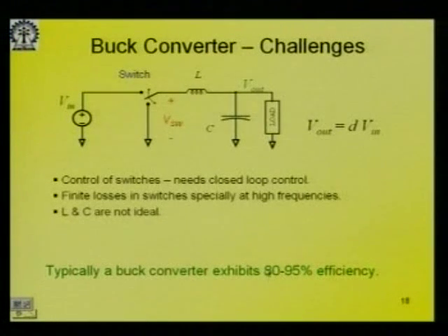Now, that may not be ideal like the efficiencies we get in transformers, which are 98% and so on, but when we work in low power mode, efficiency is certainly an issue, but apart from that, it is the losses, right. As long as you can keep these losses within control and there is no overheating, that is a reasonably good solution, right. So, we do have these as more or less acceptable. Of course, if it is more than 90, it is always better. So, these are some of the challenges in this design.